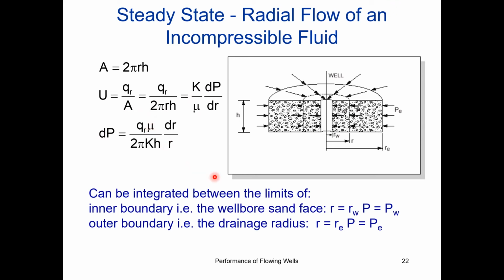This can be integrated between the sand face and the radius of the well, out to the drainage radius. So this is the drainage radius, the outer one, and this is the sand face. This is RW, this is RE.